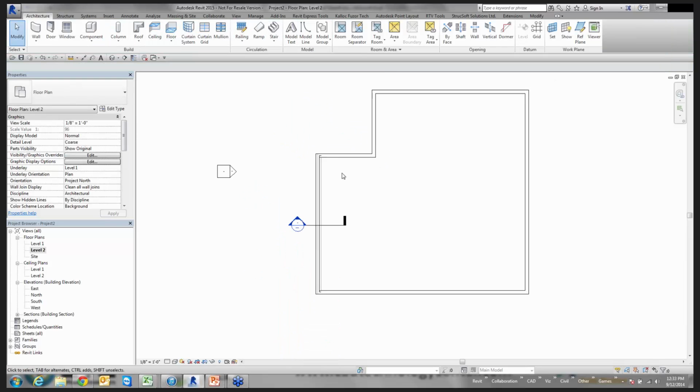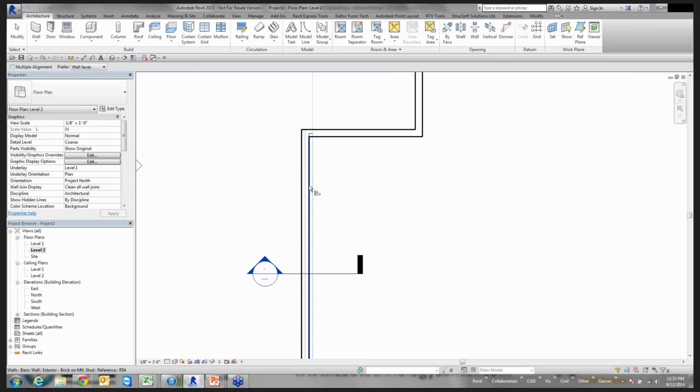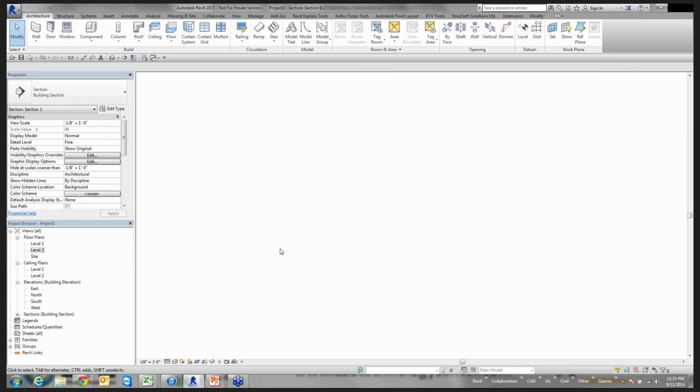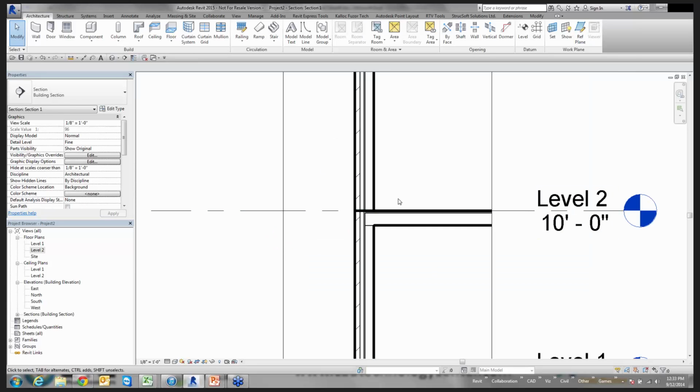And that's just the nature of the beast when you're trying to get some of the information out of Revit like we're trying to get here. I need to physically have two different walls drawn in so I'm getting accurate counts and accurate information out of this. So it involves adjusting the way you're modeling inside Revit. We have to be more thoughtful of this process so that the numbers at the end of the day are closer to being accurate, and I don't have to worry about increasing the markups as much.